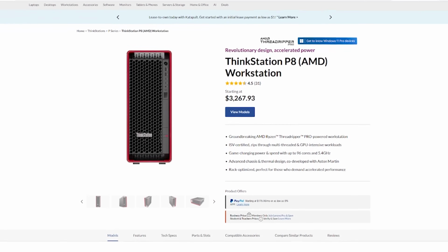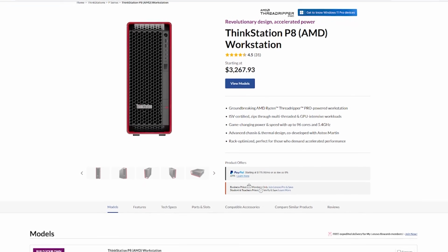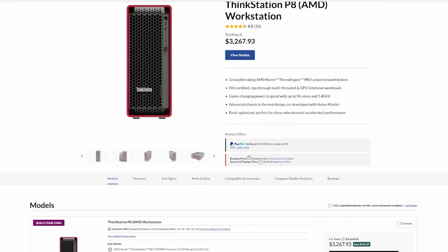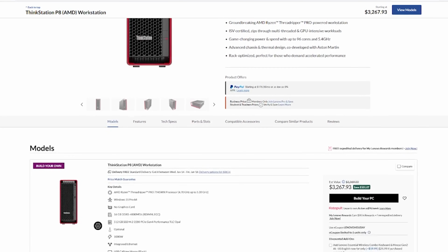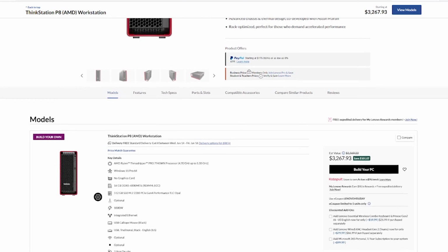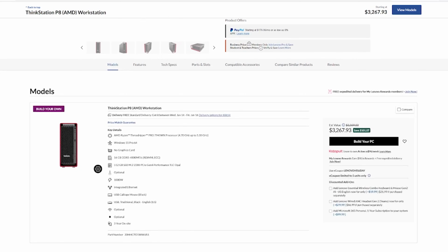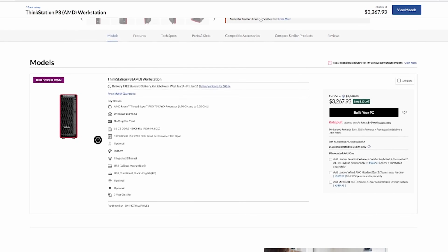I've also worked extensively with Dell and Lenovo Threadripper workstations. In those systems, the entire platform is slightly underclocked. Memory in those systems is always a ducted airflow situation, and the thermal behavior is predictable and controlled. Now, compare that to the many DIY boards and DIYers and many system integrators that have to deal with it. They get screwed, in my opinion. The DIY folks like us and integrators are screwed because the boards are not really designed for that.